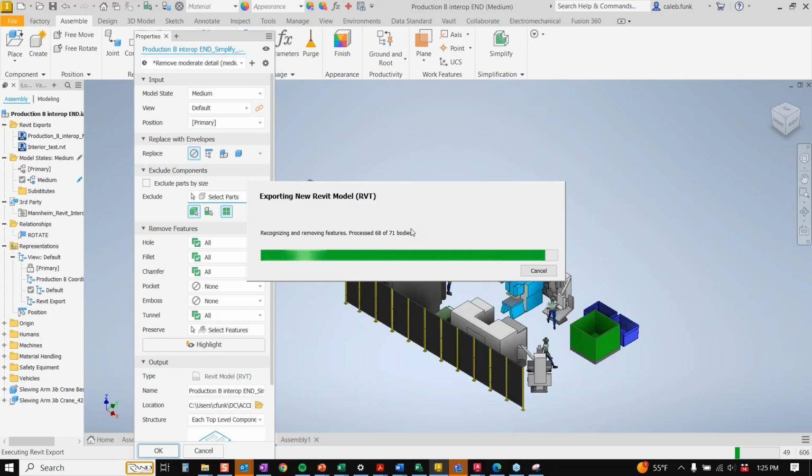And I think the linked components are a very important side of this. You're seeing my production B that Caleb went ahead and linked in. If I make changes to my model, that reference that I gave him will automatically update for him. He'll get notified that it's out of date. He can come in here and quickly update that background without having to start over and re-bring everything back in.